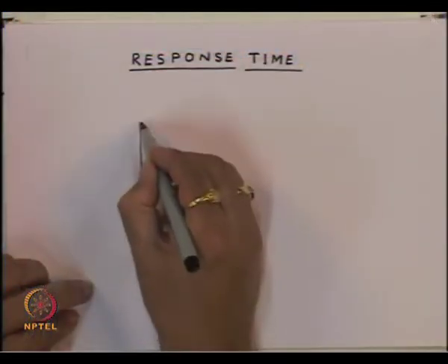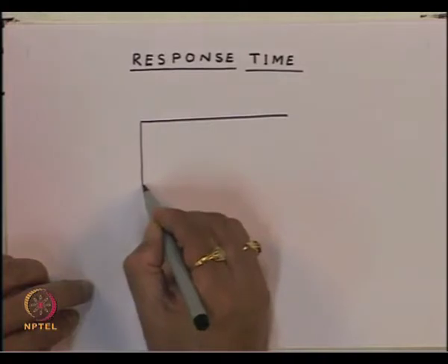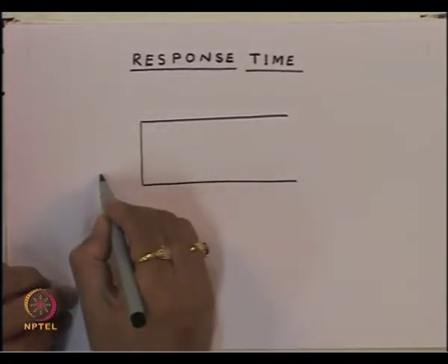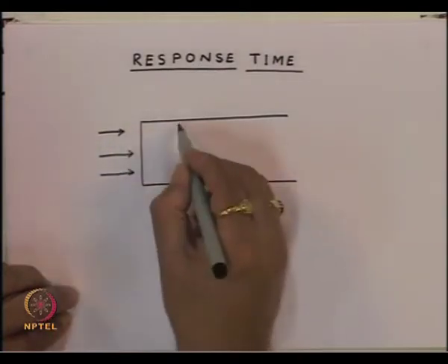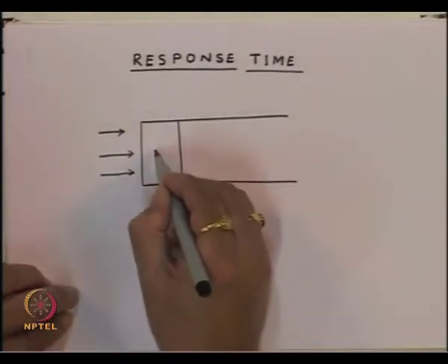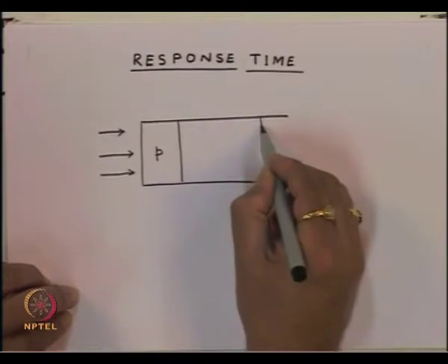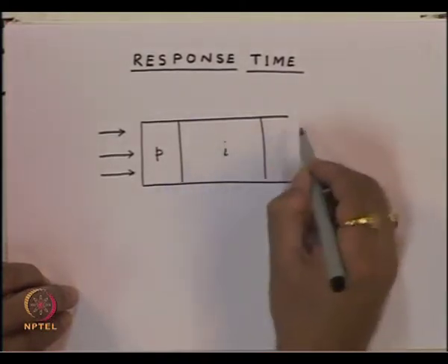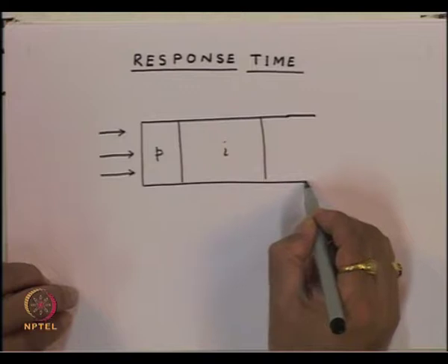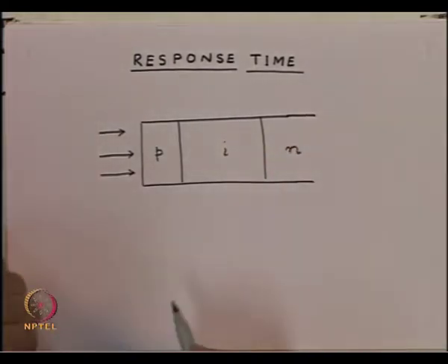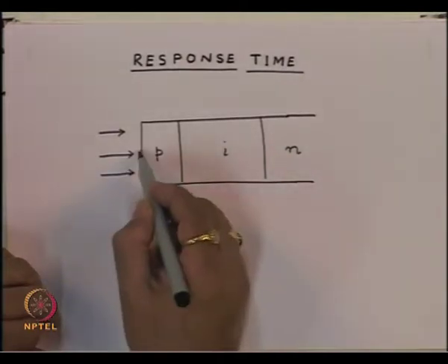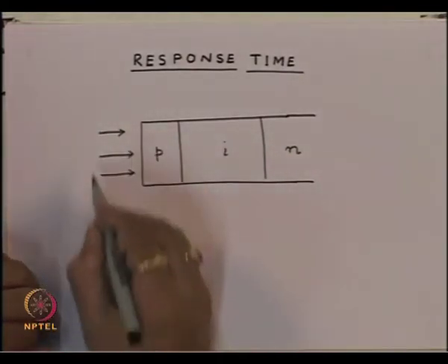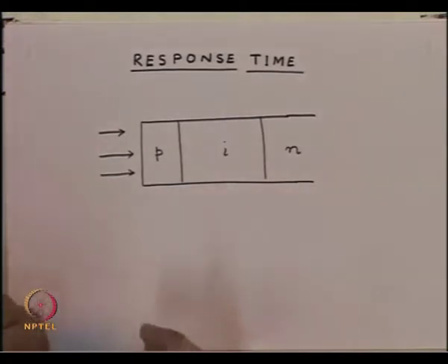So, as we have seen for a photodetector, let us say the light is incident from the p-type material. So, we have this material which is P, then we have the intrinsic layer which is I, and then we have the N material here, and this device is reverse biased, that means negative voltage is applied here, and now the photon is incident from the P side.